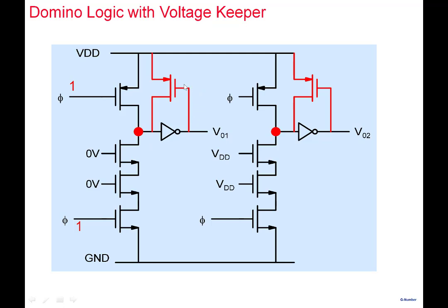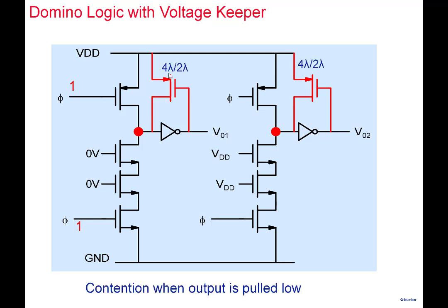The inverter is connected, and this 0 goes to a PMOS and turns the PMOS on. So this particular node is no longer floating, right? This node is connected through a PMOS to VDD here, right? And this PMOS is deliberately kept as a very small PMOS, because its role is just to supply enough current so that if there's a charge redistribution or a leakage current, this particular transistor just keeps the node at 3.3 here.